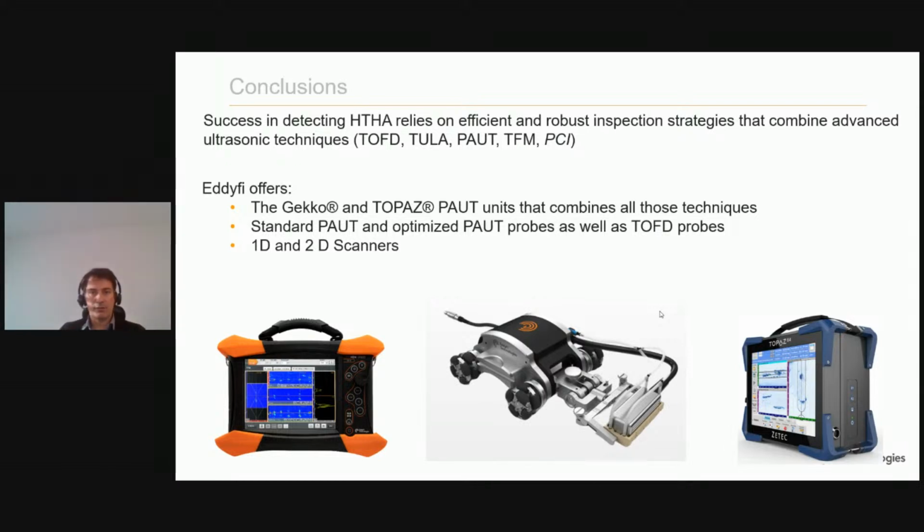Then you need to be trained on the different NDT techniques. I mean, like any NDT, you need to be trained, but you need to have access to samples with real HTHA and to have your brain trained on recognizing tough data on HTHA.